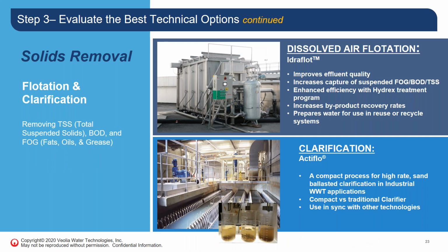In non-food and beverage facilities, on the bottom of this slide, we have our ActiFlo clarifier listed. If you don't want to float things but want to settle them, if you don't want to digest them, if they can only sink, the ActiFlo clarification process is well adapted to these types of applications. It's a compact, sand ballasted upflow clarifier that allows it to be built with a very small footprint. And when it comes to reuse and reclaim situations, many plants don't have the space for these types of applications. So it helps to be able to have a smaller footprint.